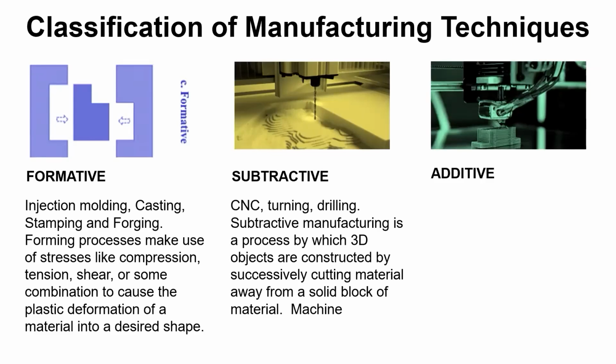And then you have to talk about the formative, which is best suited for high volume production of the same parts, requiring large initial investments in tooling like the molds, but then being able to produce parts quickly and at a very low unit price.